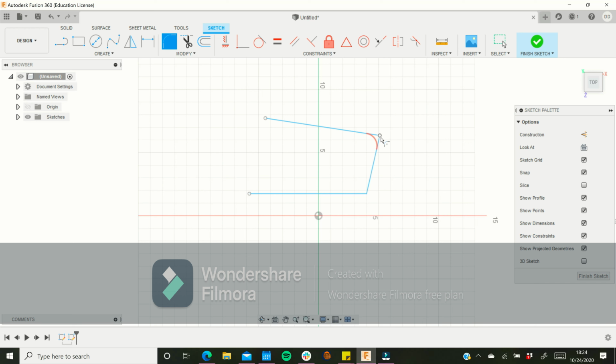With a fillet, fillets are very important because, first of all, they can be better for design. You don't always want sharp corners and sharp edges on things for whatever reason. You can come up with any number of reasons for why you might not want those. But they're also very important because when water jetting parts, which you're going to water jet a lot of things if you become involved in motorsports and if you're machining in life, the water jet, no matter what, will always make some sort of rounded edge where a point or a corner used to be, because that's just how the water jet works. So to get ahead of the curve or to eliminate that from happening, you can make your own fillet, and the water jet will be able to accommodate that very nicely.